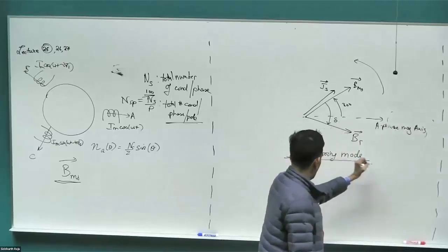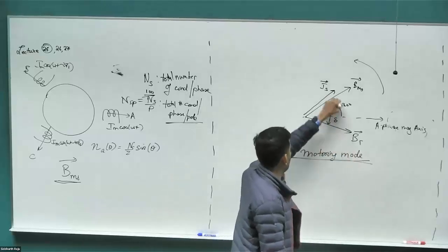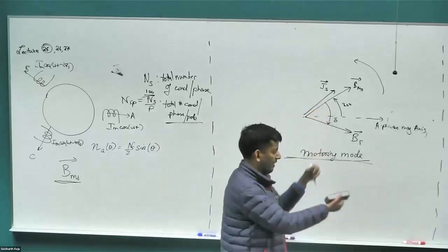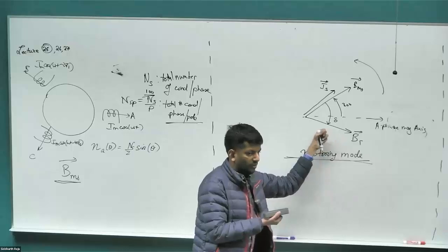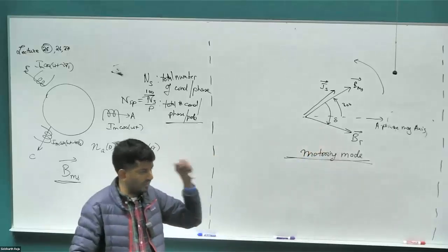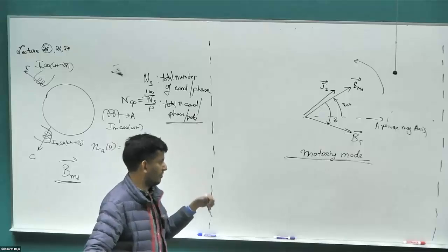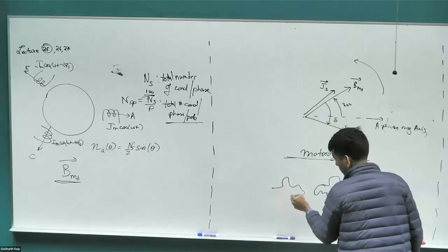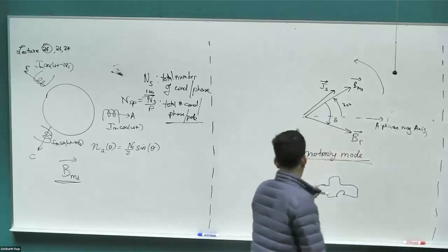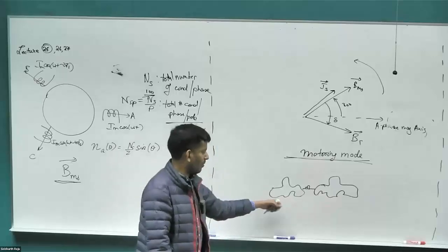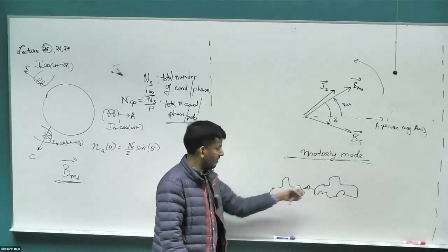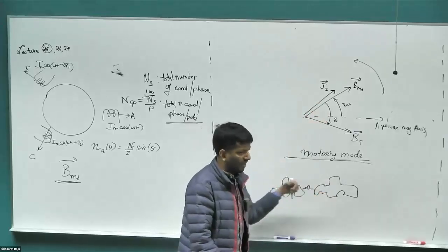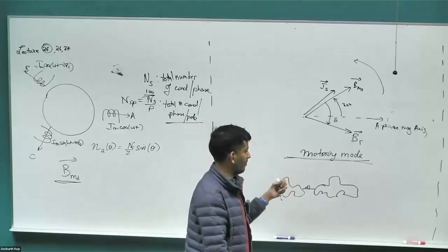Okay. But again, it's very critical that you remember at steady state, all of these space vectors are rotating at the same speed. Right? So you can have an angle difference between these two. It can lag behind, but they are rotating at the same speed. So think of like you are going in a car and you're towing something in the bed behind your car, connected to some spring. Both of the cars at steady state must be at the same speed. Now, instead of towing a car, let's say you're towing some big truck. The spring is going to be stretched. Your load angle is going to be larger, right? But both the truck and the car would have to go at the same speed at steady state. That would be the requirement for steady state.